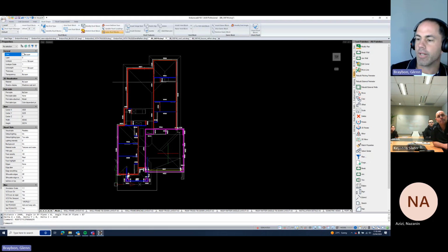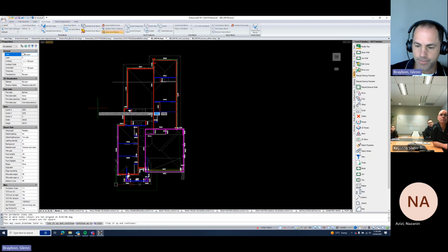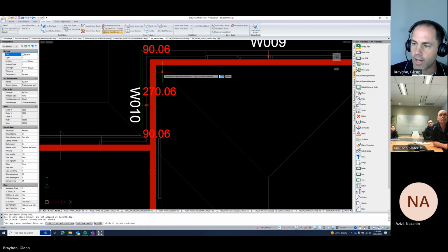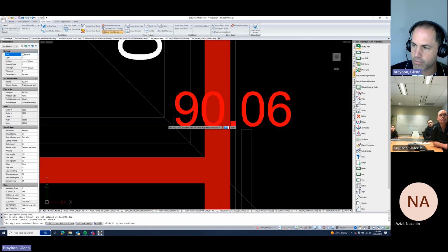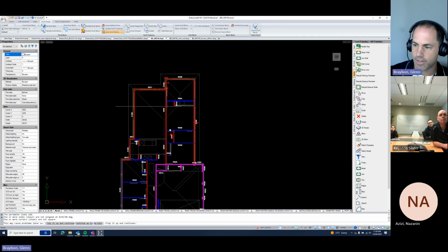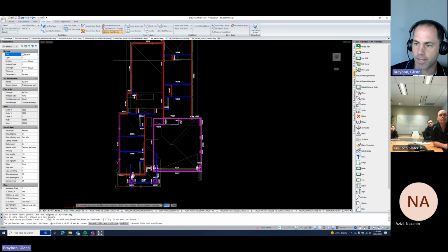So we've got our pitching perimeter in the right spot. We've adjusted it. You guys obviously do a lot of adjustment of that pitching perimeter, so it would be great to get some feedback around that. But then we're building the roof block, whole shape. I've obviously made a mistake somewhere, in some right angles, maybe the CAD's a bit wrong. I've obviously snapped to a wrong point down there. It's exactly the same as EnduroCAD. Tidy it up and continue. The perimeter was corrected. Accept this and continue.